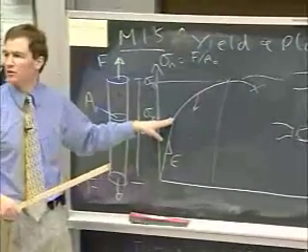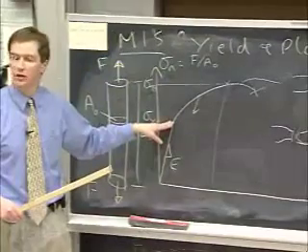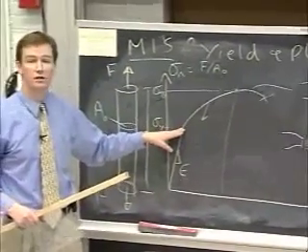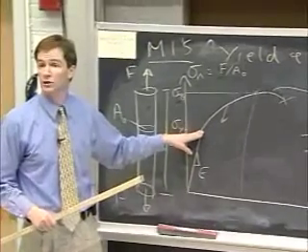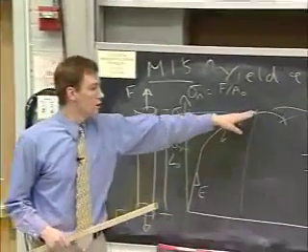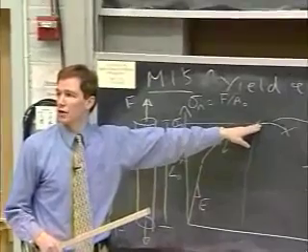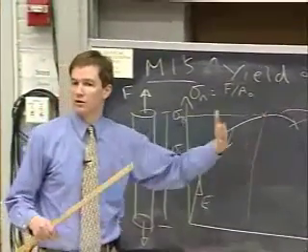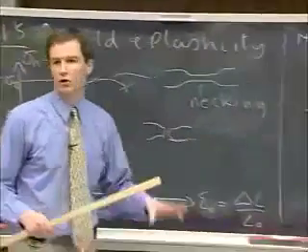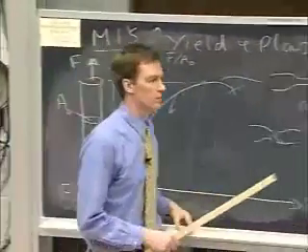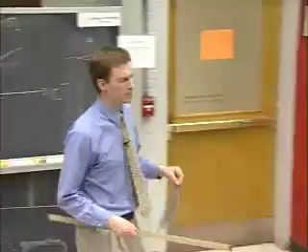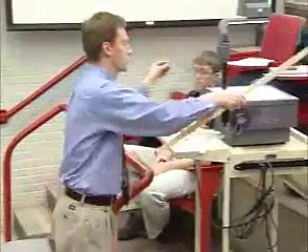Generally for aerospace design, we are going to design so our material remains pretty much everywhere below its yield strength. And we're going to rely on the fact that there's some tensile strength, a higher quantity, that is there to bail us out if we get an unexpected overload. And we'll come on to talk about the concepts of limit and ultimate load on a structure in due course.